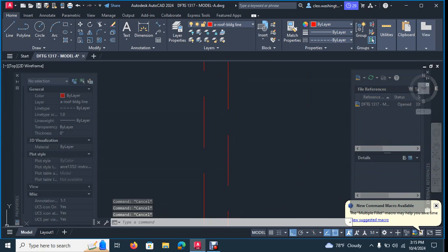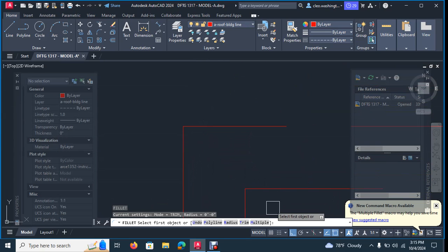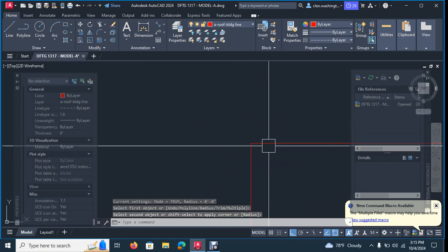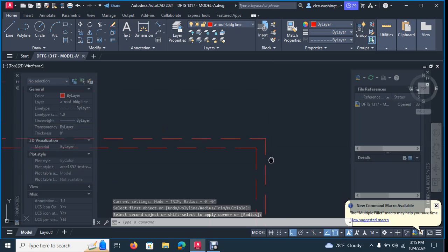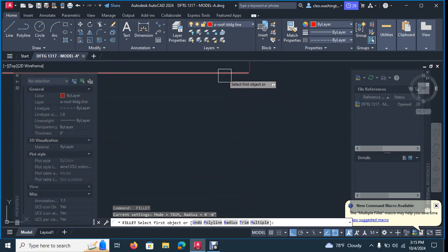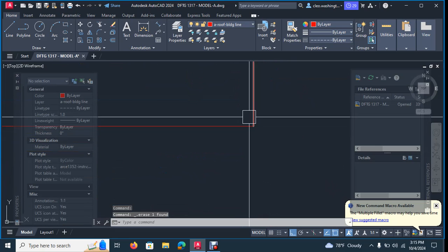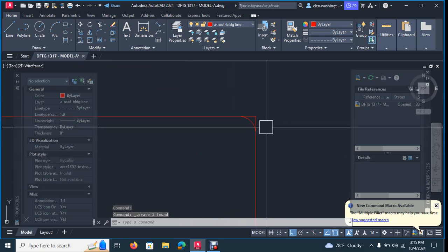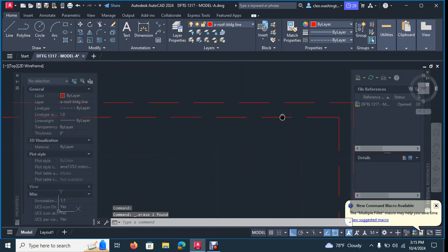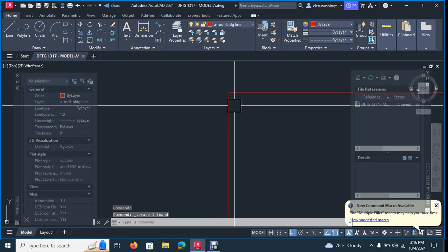And generally you'll use that when you're drawing something with a radius on it. So type in F for fillet. The standard default setting is now set for no radius at all. Okay, hit the F button again. All right, so now let's go ahead and delete those radius out of there because we don't need to see it, right? Let's click here, delete that out of there.